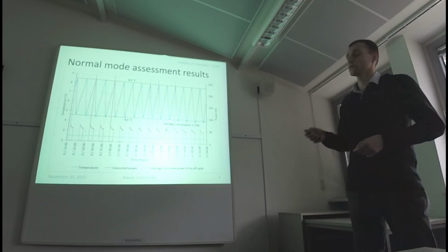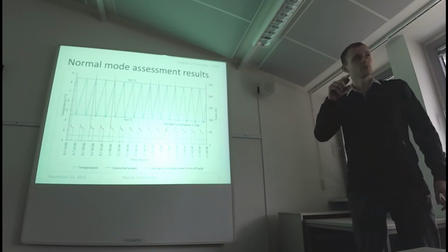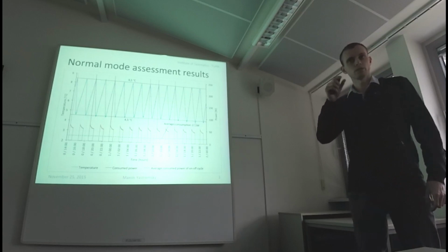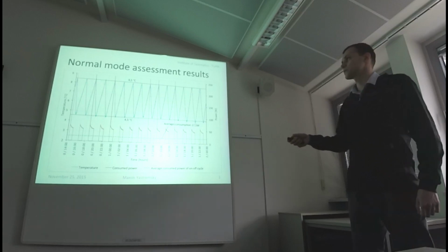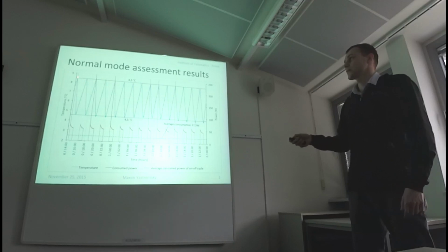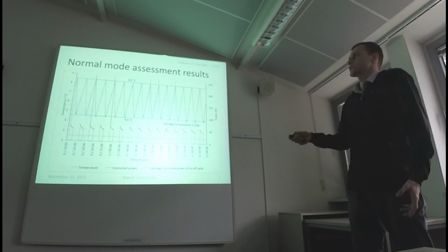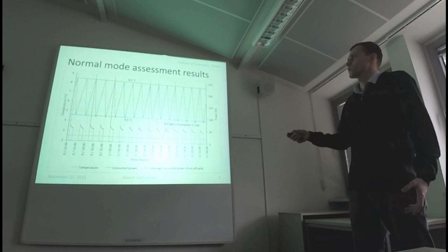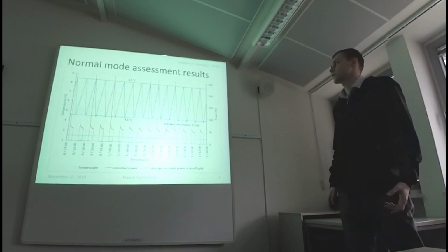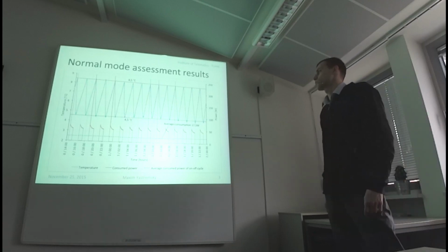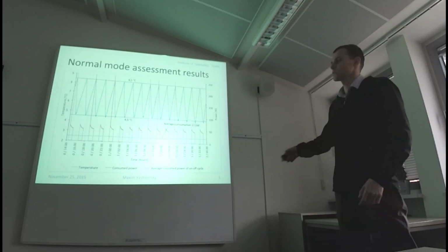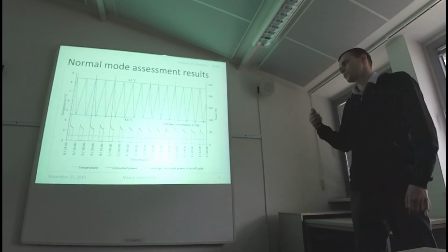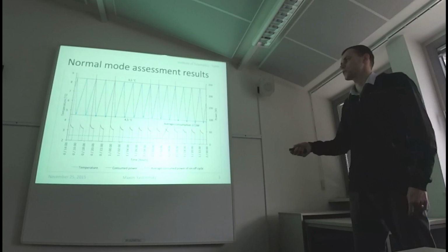So this was level 3 of the inner thermostat of the refrigerator. I set it as level 3, and that showed that the upper temperature is more or less stable, and it was 8.5, and the lower 4.5, and the power consumption is also periodic, and this period is more or less stable.